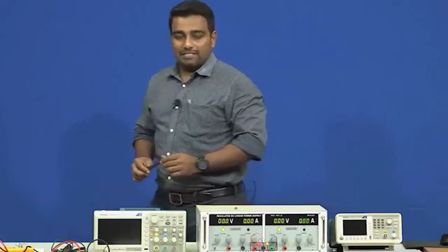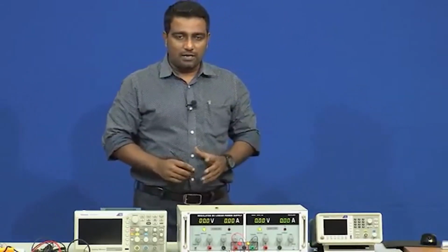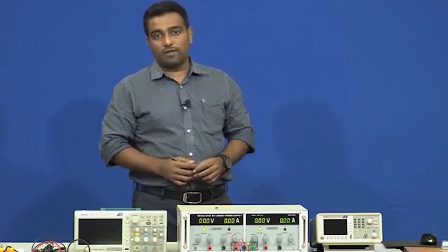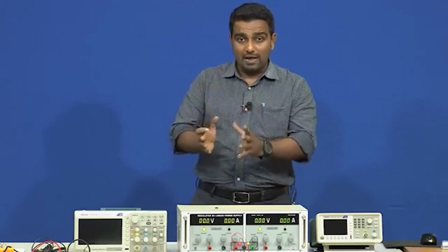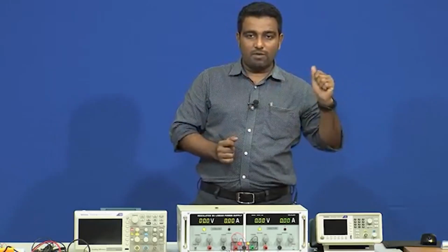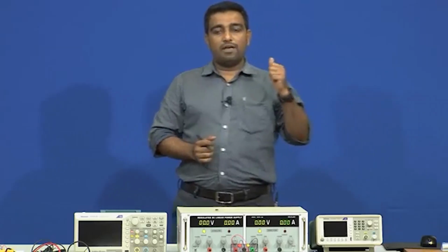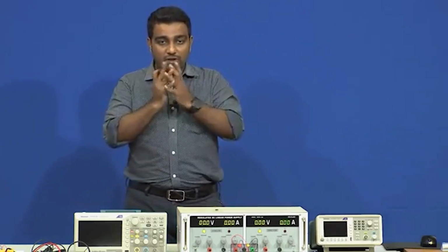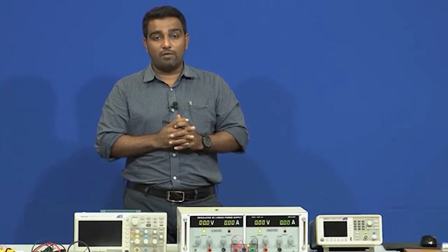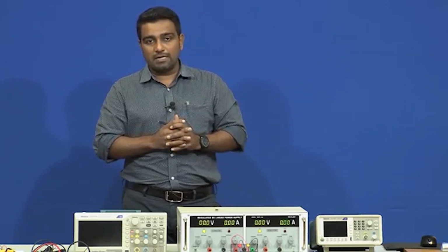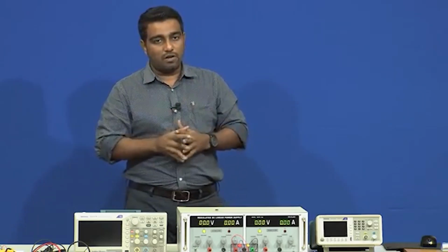So, last lecture we have seen the input bias current, right. This lecture let us concentrate on input offset current. We were able to measure the input bias current. I have shown you the table where you can measure V plus, the voltage at the non-inverting terminal, then V minus, the voltage at the inverting terminal, then we understood how to calculate IB plus and IB minus, and then the mode of IB plus, IB minus divided by 2, that was your input bias current.